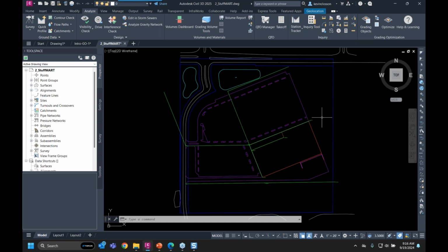We had the elevation of the building, so then we took that and we knew the length of the parking lot, so we would offset that at a distance of whatever it was. I can't remember what it was, 500 feet, something like that, and it was a negative 2%. And in this case, all of this was projecting downhill to the northwest sort of deal.